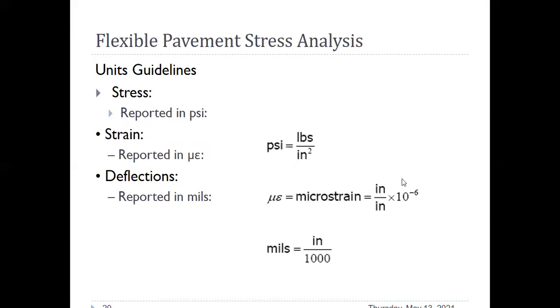So let's once again review that in flexible pavement we calculate stress, strain, and deflections. Stress we report in psi, strain in microstrain, and deflections in mils.